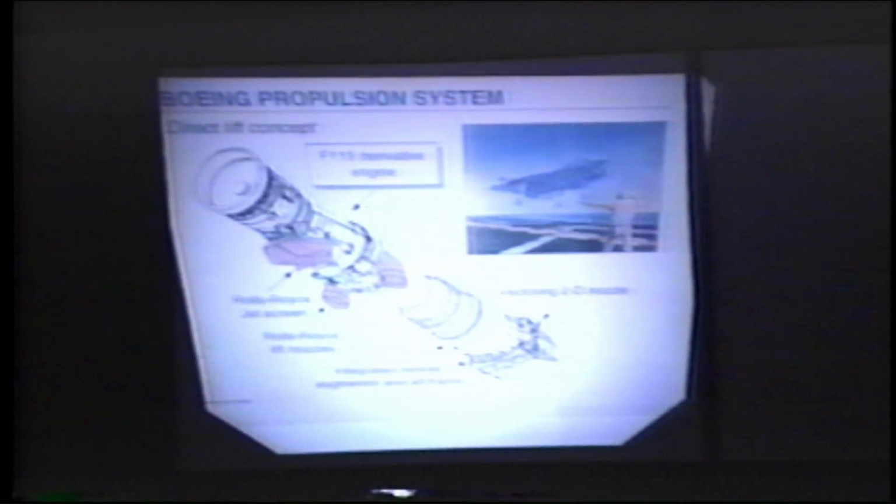By having that extra stage, we spool up very quickly, and we do have the energy so that we will have good thrust response for the pilot. Now, when we're in the VTOL mode and when we're in the CV mode, these components just aren't there. So it's essentially a common engine, and we remove these components, and you saw a few little pipes that come out the back. So we have a very common engine in all three of the variants.